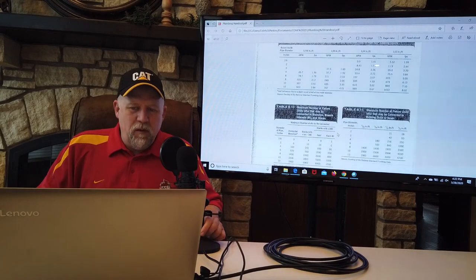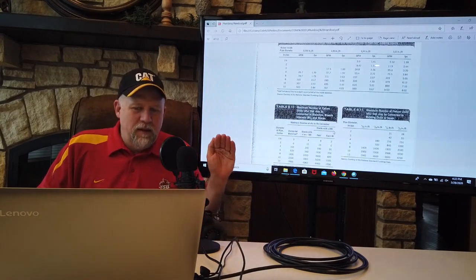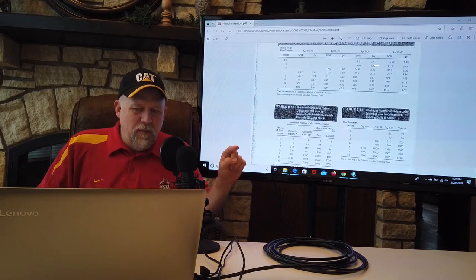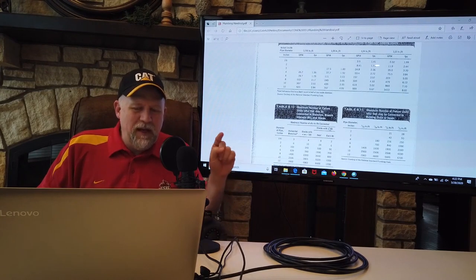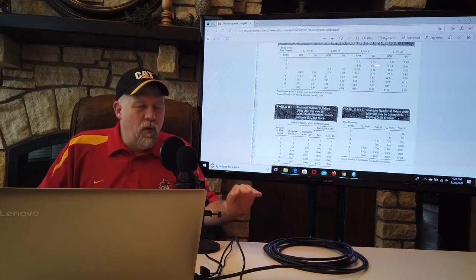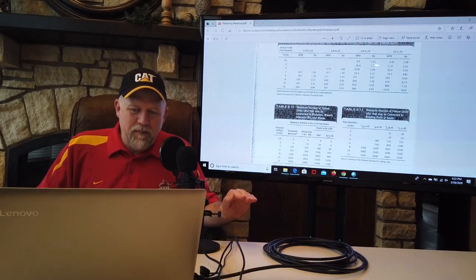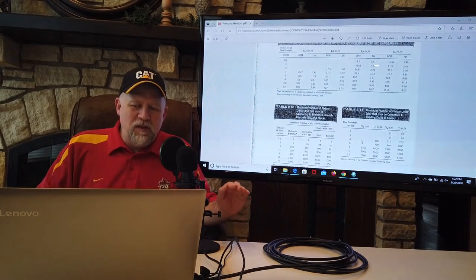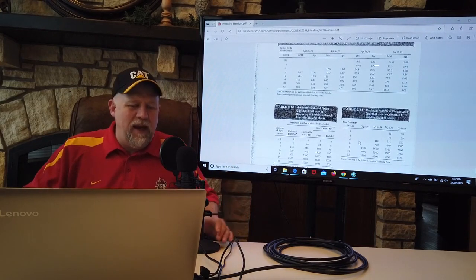All right. So the progression: find the occupancy, determine the number of fixtures, multiply the number of fixtures by the drainage fixture units each, add them up for your building, and then use table 8.11 to size the sewer main.